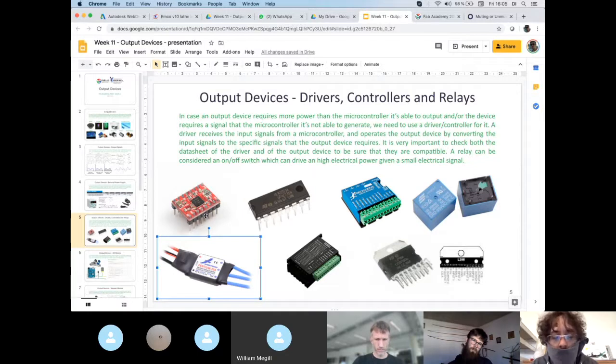So in some electronic speed controllers, you have the advantage of an integrated step-down voltage regulator. This means that the electronic speed controller can give power to your microcontroller or to the logic of your project. So in the case, for example, of you, Hannes, for your DPV, it's possible that if we have to use a brushless motor, we use an electronic speed controller with a step-down voltage regulator inside.